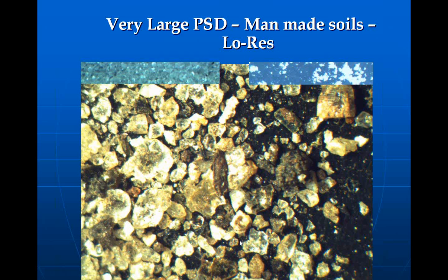This material came off of a small commercial site. This is probably almost 100% constructed soils, amended soils, places where the landscape folks brought in vermiculite and peat and whatever they needed to do for moisture content. They bought sand, they mixed it, and they wanted to have drought-tolerant soils and urban-tolerant soils to put in their flower beds so that everything grew nice and looked nice. If you look at the particle sizes here, you've got 1,000, 2,000 microns. This is really, really large compared to the stuff that's coming off natural soils.